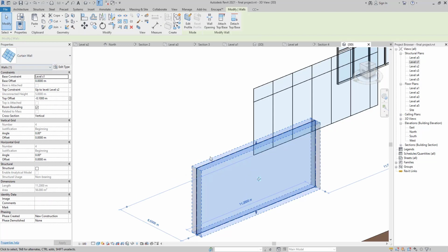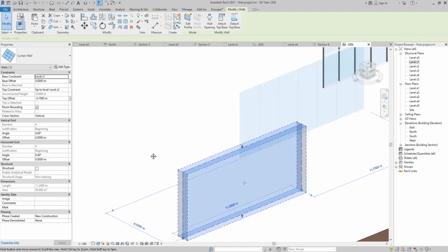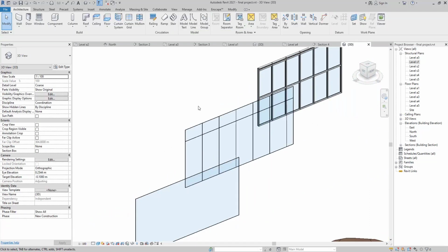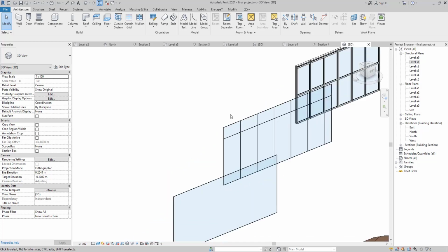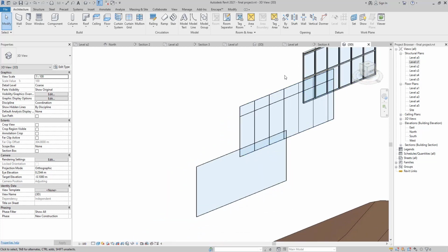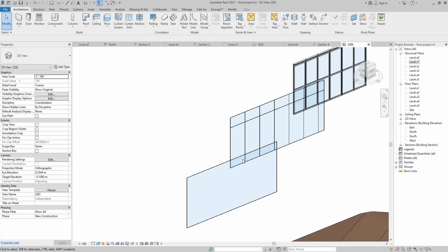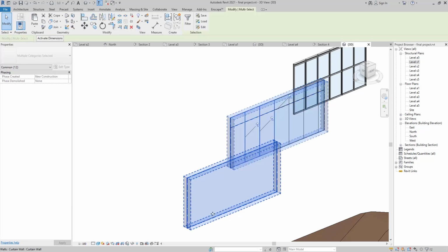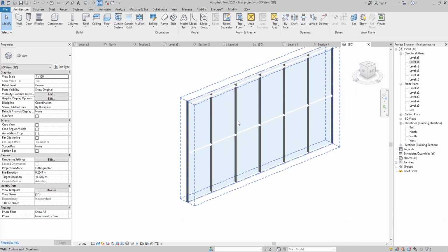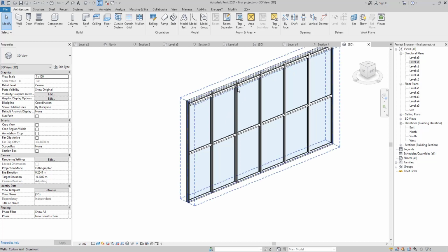Here we are going to have just curtain wall. It's just a glass. It is also useful. Sometimes we can use it because we are, for example, going to design a glass pattern or glass window as we wish, and we don't want to have any mullion. The first one we are going to work with because it has the most usage, and the other ones we are going to use and learn about mostly when we use them in our project. Because this one includes all of the settings of the other ones.